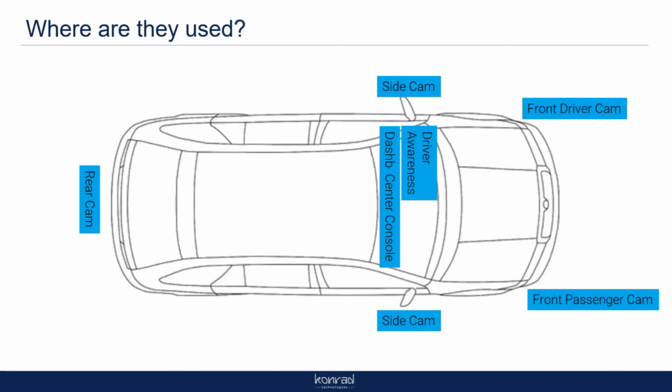Now, no 2 cameras are equal. This is the really interesting part. On that system that we worked on that had 11 cameras, 5 were of one type. Those were basically our surround view cameras, the ones on the side and in the front. The cameras in vehicle were much lower resolution and slower frame rate. And the trailering cameras were a little bit lower resolution and frame rate. So in the end, they had 11 cameras, but only 5 different camera sensor types. So you got to watch as well, because different resolutions, different frame rates, depending on the application, it can all change.